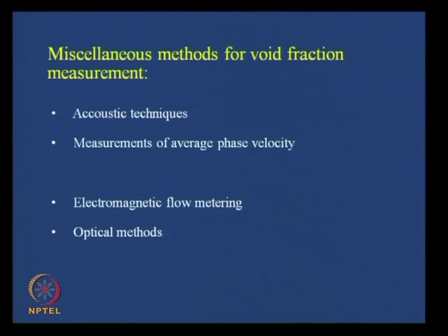Certain other techniques: if we can use the amount of radiation absorbed, we can also use the amount of sound wave which is absorbed. We can find out the velocity of sound. We very well know the velocity of sound is a function of the medium through which it is travelling. This is a very well known fact. So, through water it will travel fast, through air it will travel slow, through a two phase mixture it will be something intermediate. So, we can measure the velocity and try to find out alpha there.